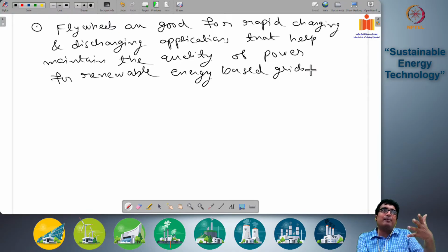And then if the supply suddenly decreases and the demand spikes, you again re-engage the flywheel shaft with the generator shaft and transmit some of the rotational energy of the flywheel into the generator to keep the generator rotational motion constant. So the generator rotational motion is being kept relatively constant to provide high quality power that matches with the demand. So small scale demand supply fluctuations can be made uniform.